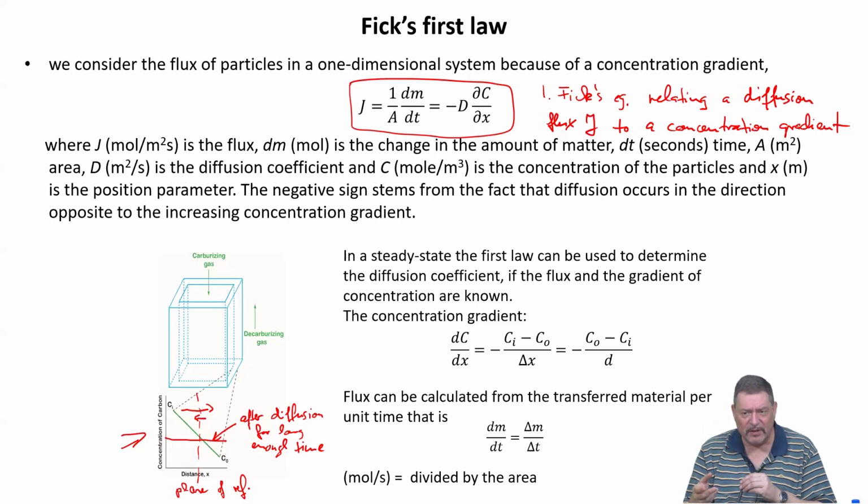Diffusion will always be there, but a diffusion flux requires a concentration gradient, if we just stick to this phenomenological explanation by Fick. We will later on in this lecture see that concentration gradient can be deceptive as a determining quantity, and we better use the gradient of the chemical potential.